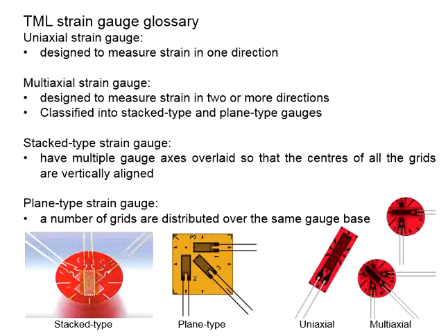Now for the multi-axial strain gauge, you will need to determine which type of strain gauge you are using, depending on the situation. If you are measuring an exact point in various directions, probably the staggered type of strain gauge will be more suitable. But if you are measuring a regional type of strain with reference to one specific point, then you may consider using the plain type of strain gauge.